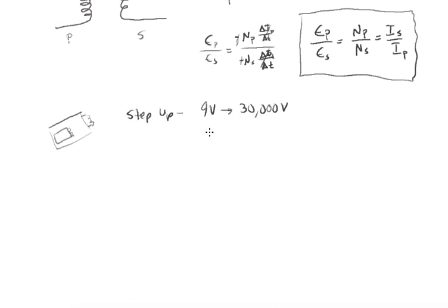And so that means that your primary current, whatever it happens to be, is going to drop down and you're going to have a very, very low, with that big of a change, you're going to have a very low secondary current, because current's really what's dangerous, and that's what's supposed to make these non-lethal. You have a big voltage, so even if you have to shock your attacker through their thick coat, it'll still work. But a very small current, so it won't actually stop their heart or kill them, because current is the dangerous thing. So really high current, low voltage.